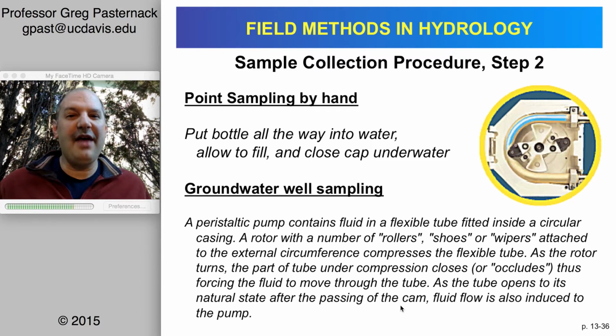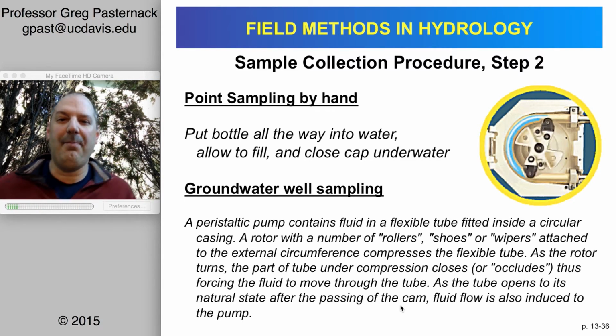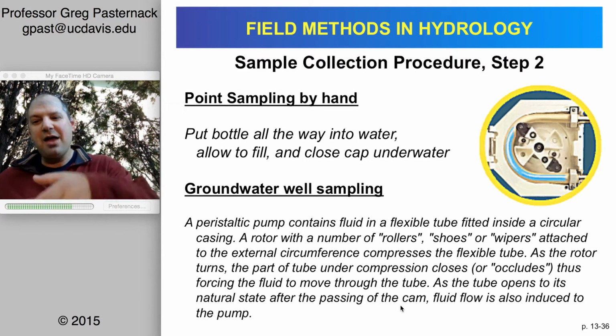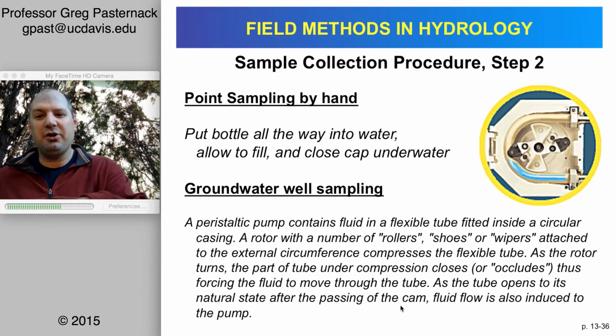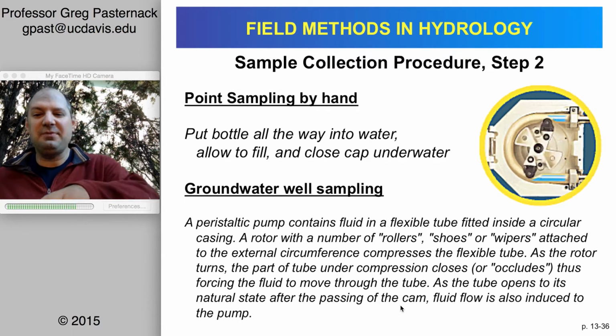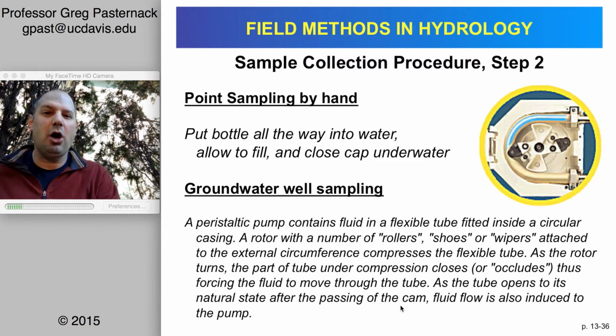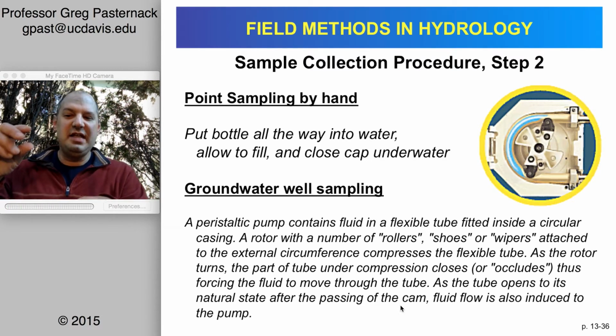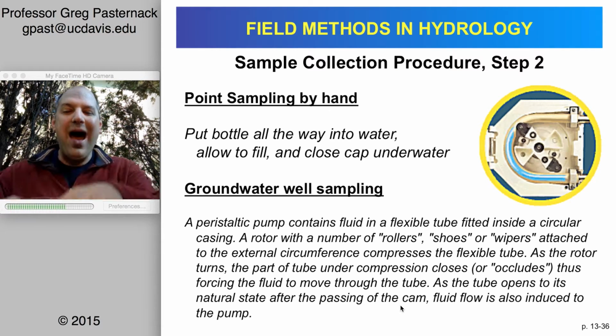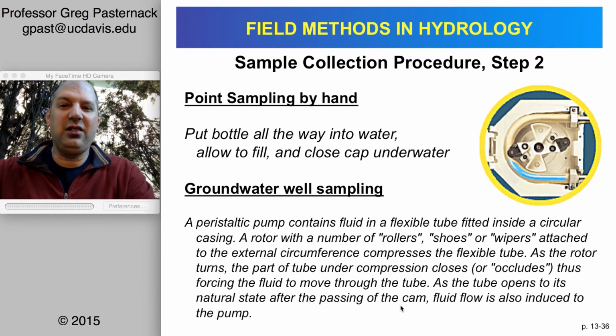The most common way of getting a sample is to have a bottle, put the bottle entirely into the water, turn it upside down, right side up to make sure that it's fully immersed and all air bubbles are gone. Take the lid in your other hand. While it's underwater, close it.